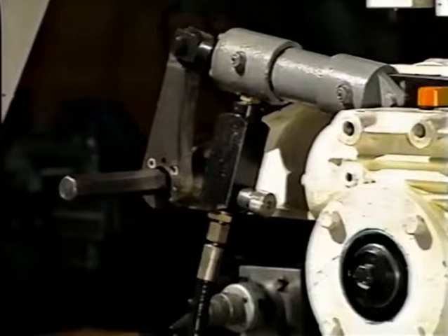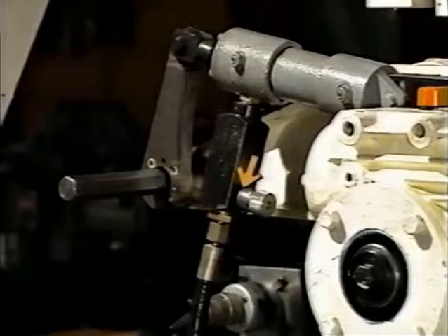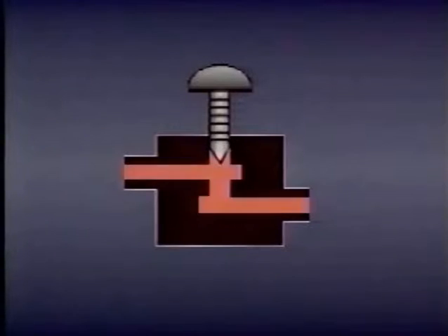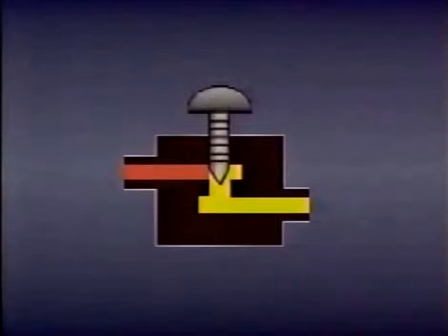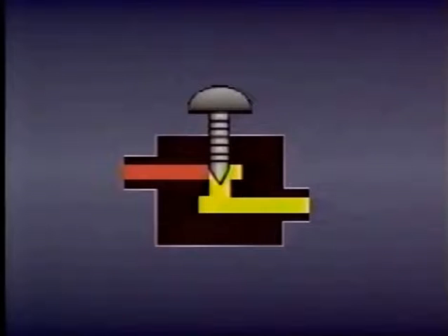These valves consist of a valve body and an internal part which moves in and out of an orifice. In one of its simplest forms, a flow control valve has a threaded rod with a tapered nose or needle which can be adjusted in or out to change the flow. Adjusting the needle varies the flow restriction, increasing or decreasing the flow rate through the orifice in the valve.